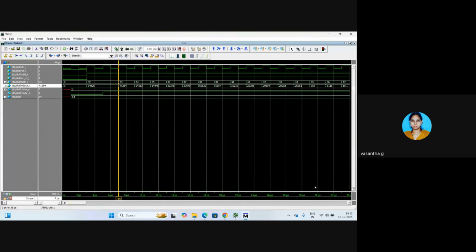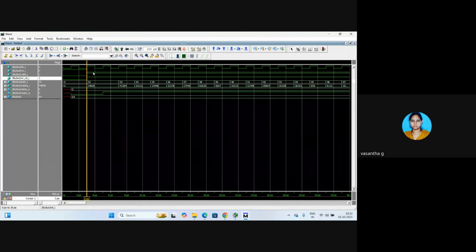Same thing, you have to read it. So where is the read data? Write read enable is 0. Here write read enable is 1, which means we are writing into the memory. At that time reset should be low, right? Here reset is low only. See, you can see the value here. Reset is low, then only we are able to write. If reset is applied, everything should come to 0. The values we are getting are 0 here. But when reset is 0, then we can do whatever write logic and read logic. That is the concept we have learned in the notes.